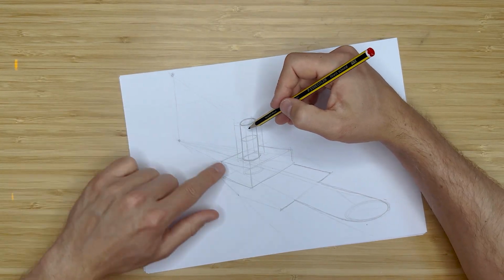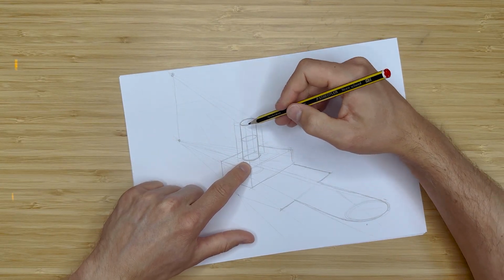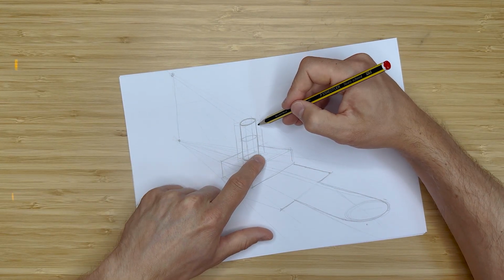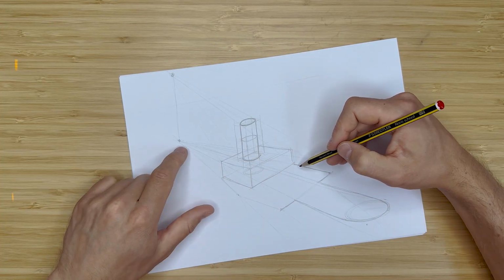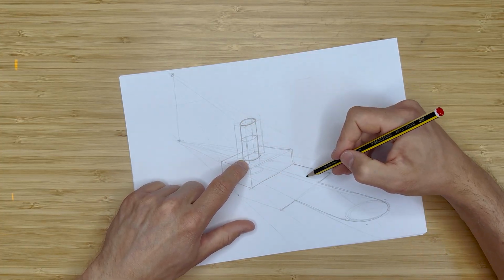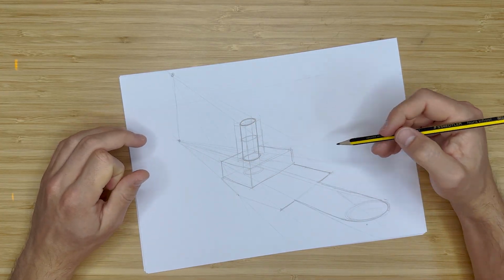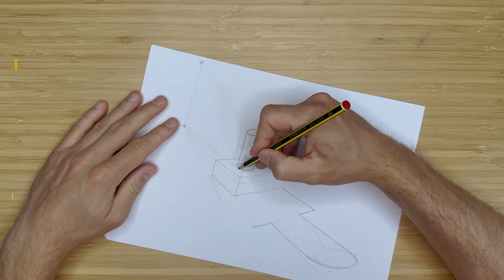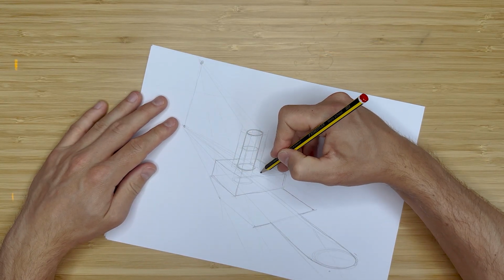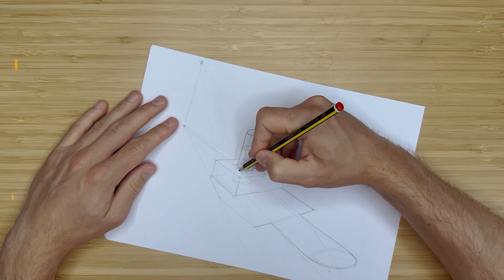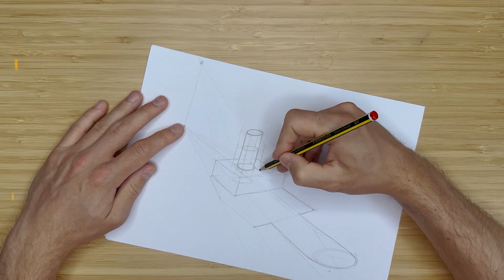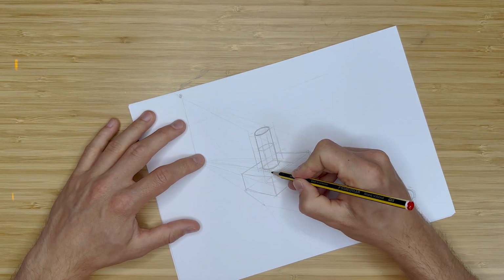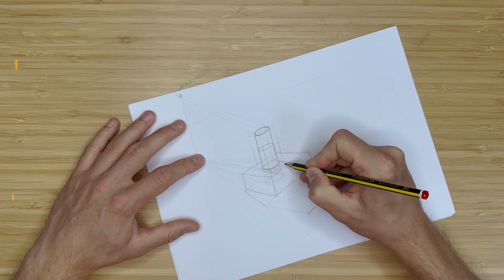This top one, for this face, we don't see it. Does that part affect it? No, it comes down the inside of the shadow. This one comes down the inside of this main shadow as well. So we don't actually see any of those parts. So we can basically just draw this bit in shadow as well, with the lines parallel to each other. Okay, so we've got shadow there.